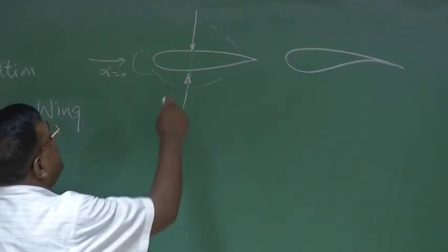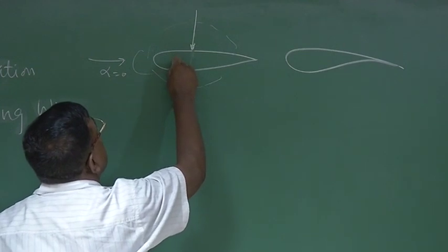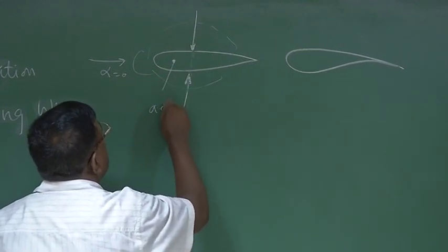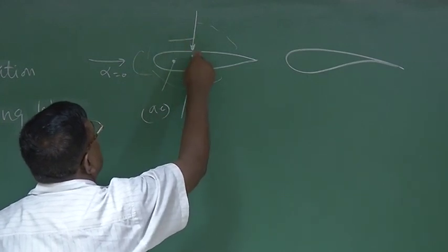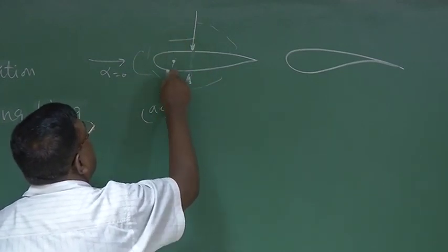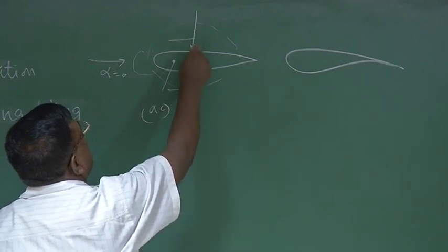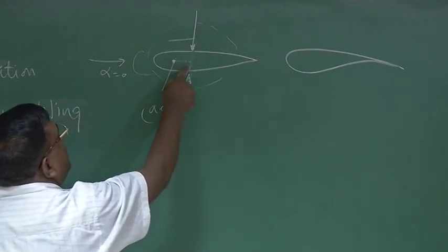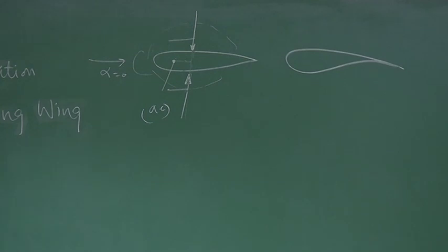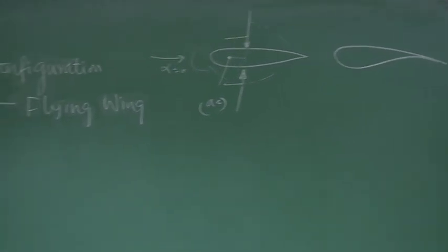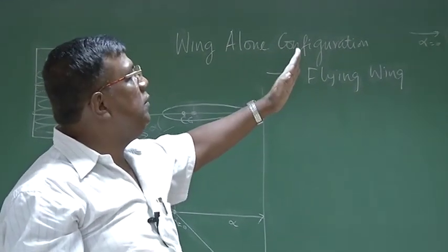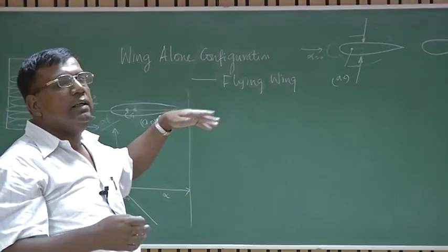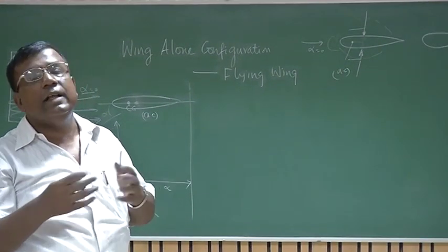So if I am transferring this whole force combination to the aerodynamic center, you know I have to transfer it by a force and a moment. So this force comes here with a moment, and since they are opposite in nature and at the same distance from this point, the net force or net lift will be 0, and all those moments which I need to transfer when moving a force from that location to AC are also in opposite directions, so they cancel each other.